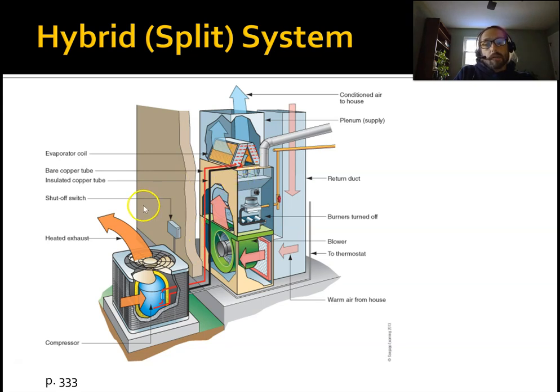And at higher outdoor air temperatures, generally speaking, your heat pump is going to be cheaper to heat the house, depending on the technology, depending on the refrigerant, depending on the age. There's all kinds of factors, but most heat pumps are going to operate pretty efficiently above 30-40 degrees outside.